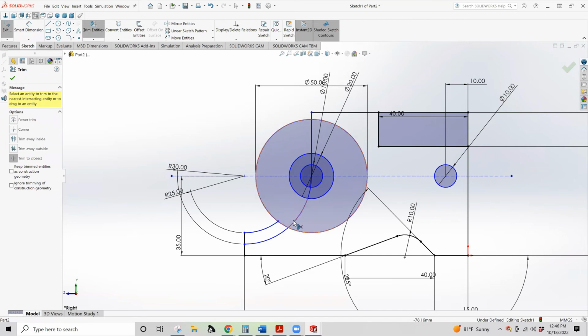So this, for instance, goes away. This goes away. That goes away. Now we'll have our recess cut. We'll do the through all holes elsewhere. That, I think, is 90+% of what we need, all in that one cut. One more.